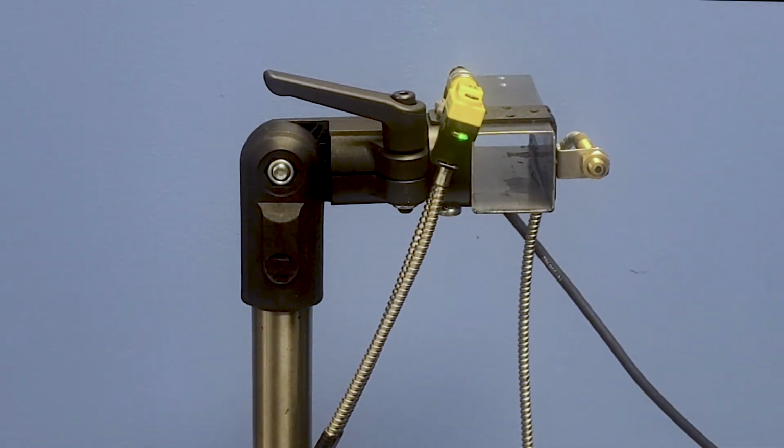Now, if that was on fall, it would be just the opposite. It would be on the trailing edge. Most applications we use are on the rise, or the leading edge. One application I could mention for the trailing edge is when you're printing on labels. Labels have a gap between them, so having the sensor on fall allows you to print on the leading edge of the next label, if that makes sense to you guys.